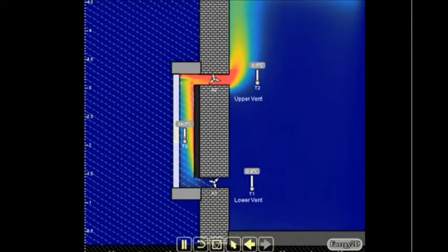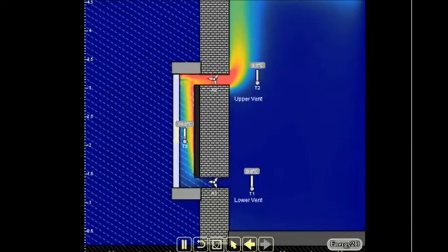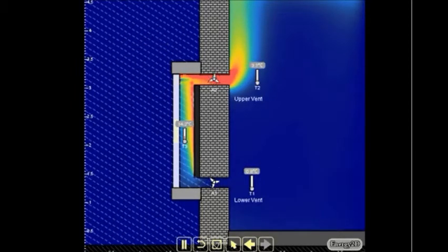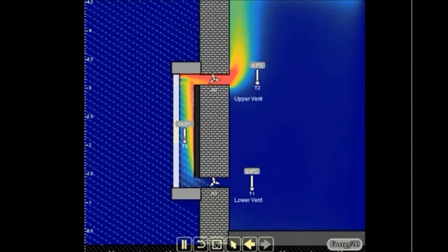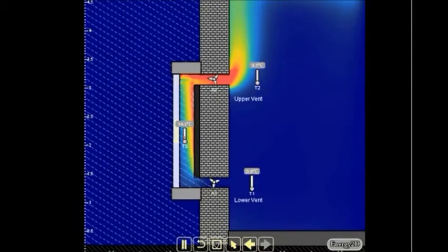Openings are made at the top and the bottom of the wall to allow for convection. The air between the wall and the single glazing gets heated up quite fast, and through the help of vents, as shown in this computer simulation, or through differences in air pressure, the hot air is constantly drawn into the interior space. For this project, trombe walls are used on the south facade on 3 different wall surfaces.